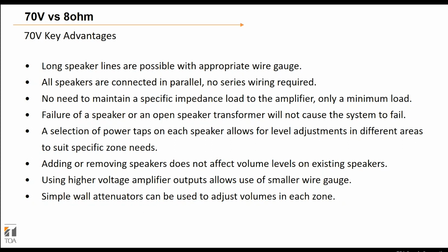We have a selection of power taps on each speaker, which allows for level adjustment in the different areas of the facility that suit specific zone needs. So that's one thing to bear in mind when we talk about wattage taps. A 70 volt speaker tends to have a maximum amount of wattage, but you do not generally need to run that maximum wattage unless you have the requirements to do so based on the job itself. So 9 times out of 10, you're setting the power draw of the speaker considerably lower than the max based on the wattage taps that are available on that speaker, and that's not something that's available from low impedance speaker systems.